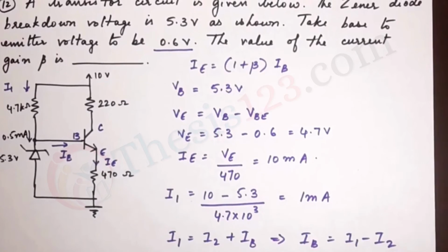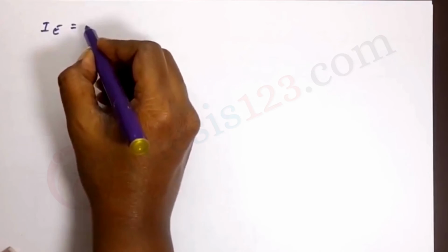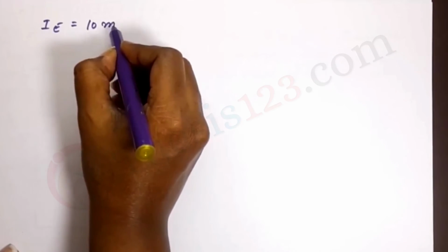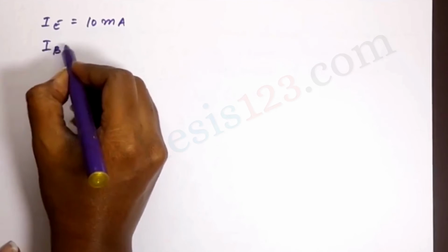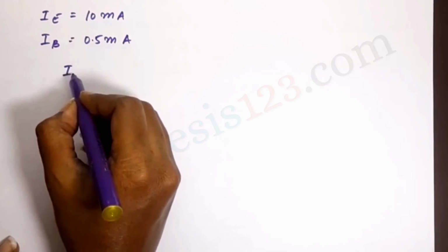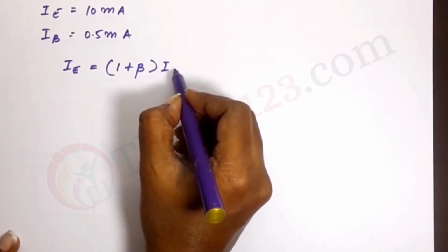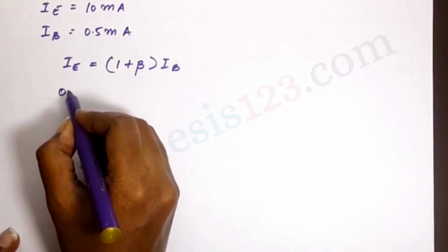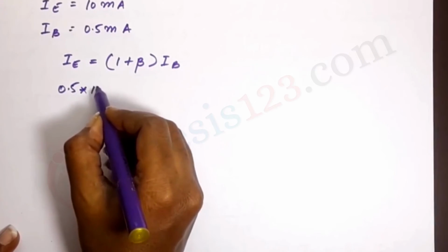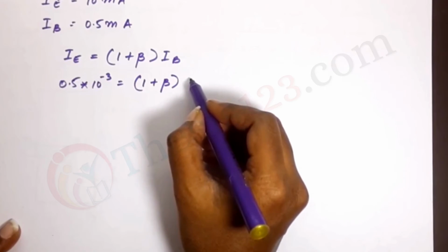Let me just take another sheet of paper here. Okay, so we have IE. IE is equal to 10 milliamps. We have IB, which is 0.5 milliamps. And now we have the formula to find out the gain. IE is equal to 1 plus beta into IB. Let's substitute. That's 0.5 into 10 power minus 3. 1 plus beta into...